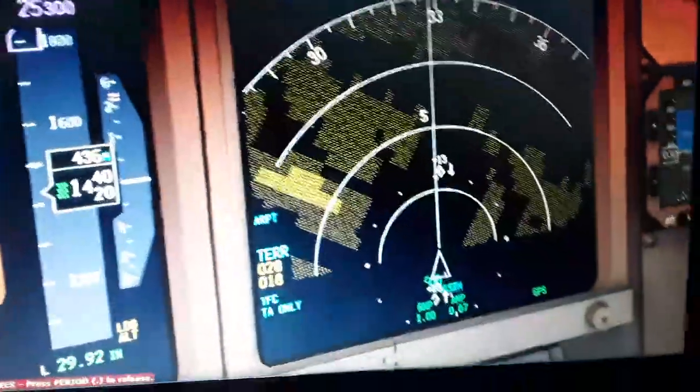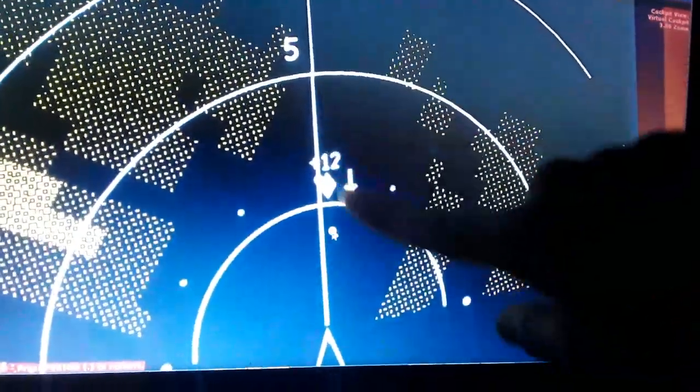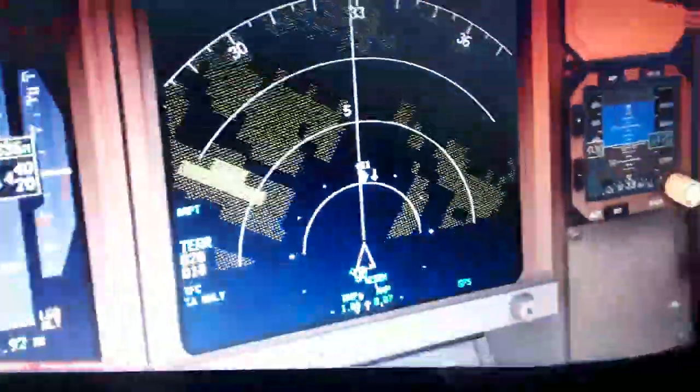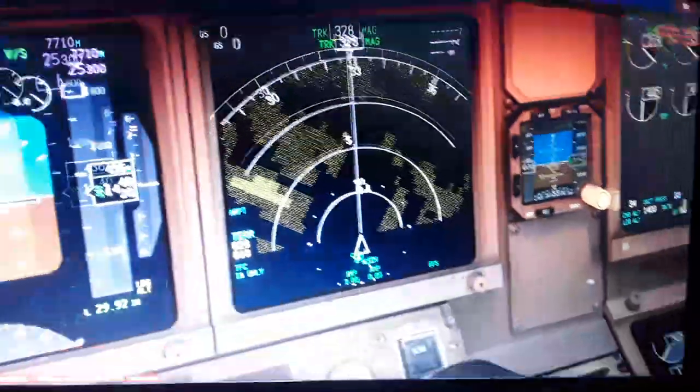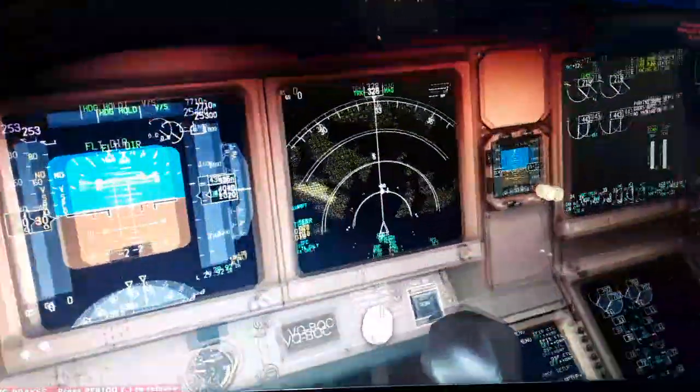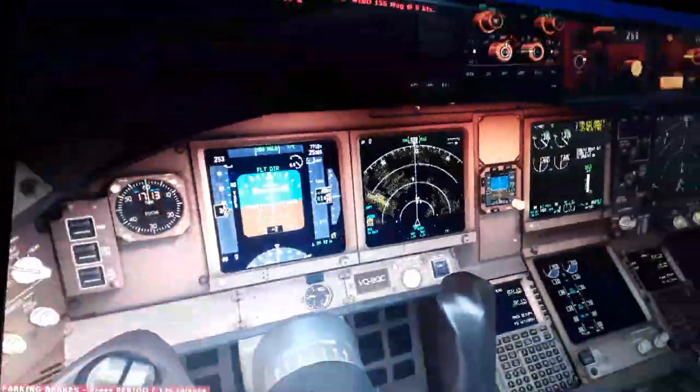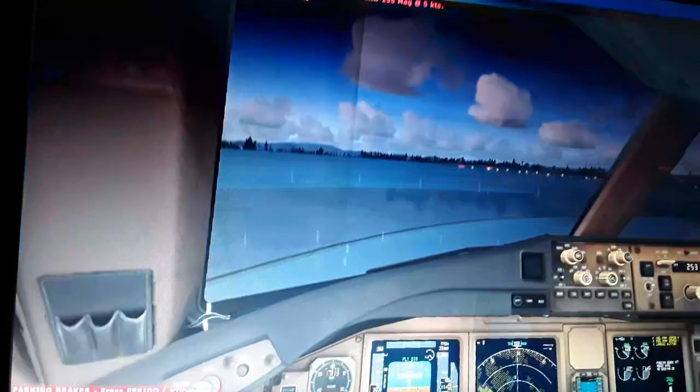The navigation display over here is plus 1000. Now we have a better view, it's plus 1200 feet. It's getting closer, it's between the 5 and the 2.5 nautical miles. It's in front of us, plus 1100. It's getting down. So this is the TCAS system and the transponder display. Other aircraft coming in. So I will show you that in a couple of seconds.